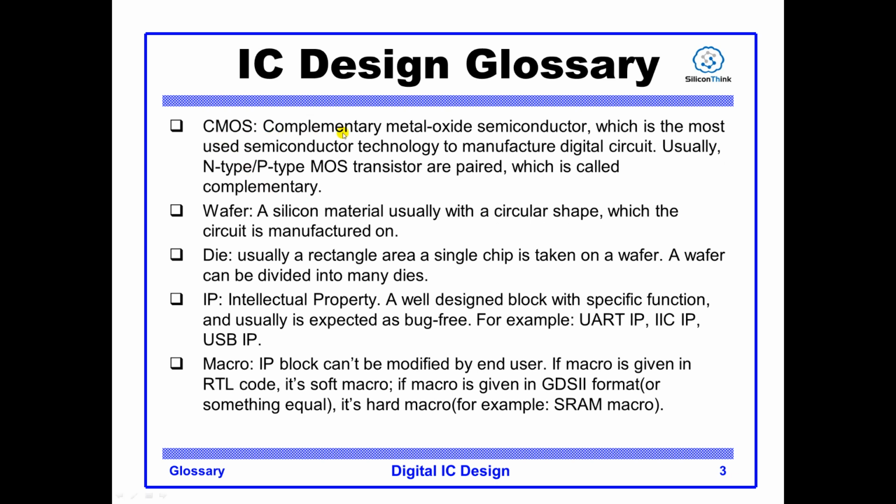CMOS, complementary metal oxide semiconductor. This is the most used semiconductor technology to manufacture digital circuits. There are usually N-type and P-type MOS transistors in a logic cell. They are always paired. One N-type cell is paired with one P-type cell. So this is called complementary.